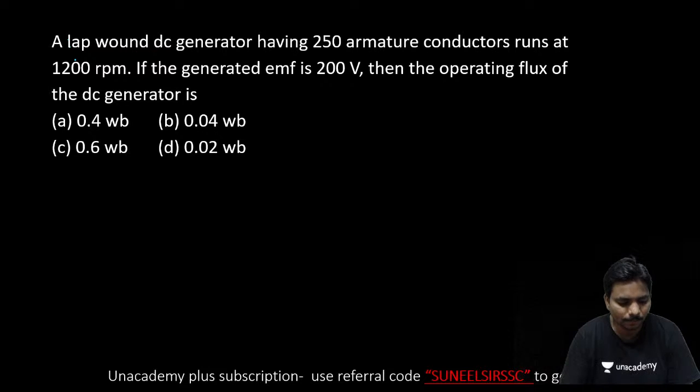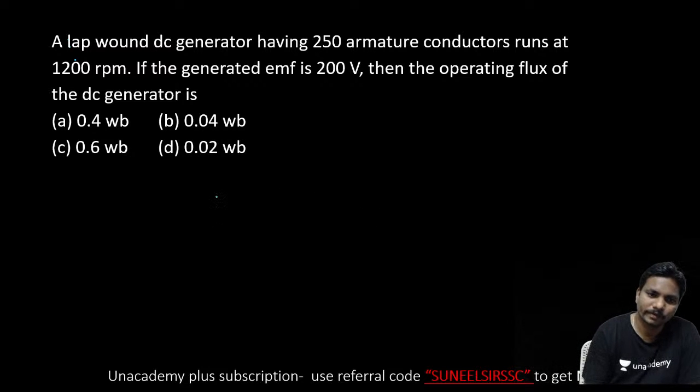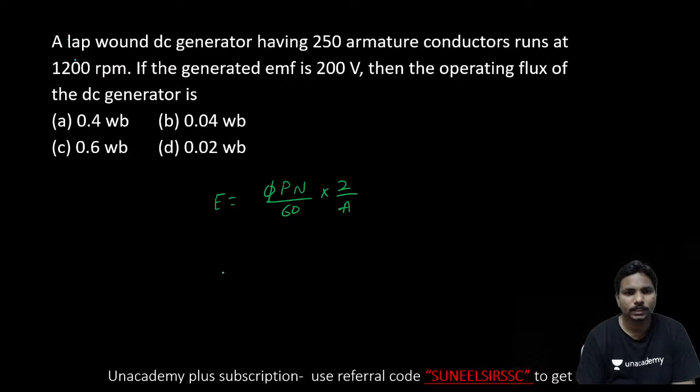Just substitute the values in the EMF equation, you will get the answer. E is equal to pi P N by 60 into Z by A. Okay, so what is the EMF they have given?